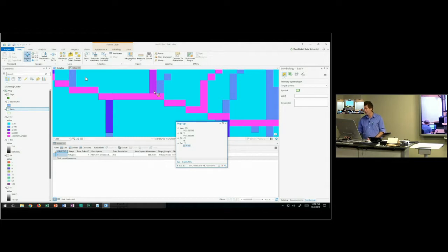Sure. So we could look at the flow direction. What is the flow direction, is it 16? Well, let's click there and see what the flow direction is. Flow direction is 4, so it's actually going straight down. So we would expect this grid cell includes this area, but this grid cell immediately to the right does not.